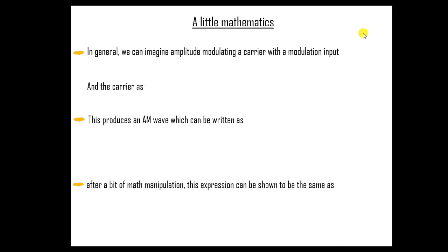We take a moment to look at the mathematics behind amplitude modulation. It is possible to write the modulating signal as this. The subscript m stands for the message signal, where all the modulation frequency components f sub m are all within some information bandwidth, which extend from about 0 Hz up to a maximum frequency f max. The summation in the equation is over the variable subscript m, where m runs from 1 to n.